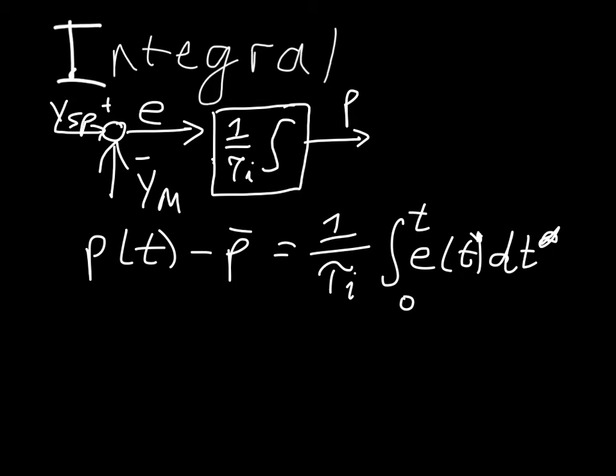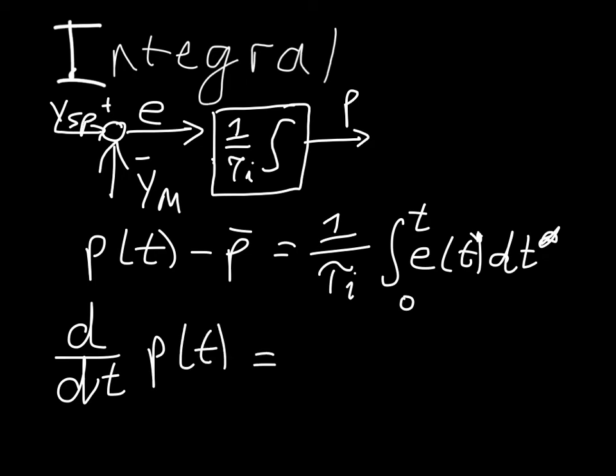Now, we can use the same trick that we used to understand proportional offset to understand the way in which the integral will reduce the error to 0, by again taking the derivative of both sides. And there we see that now we are changing proportionally to the error.